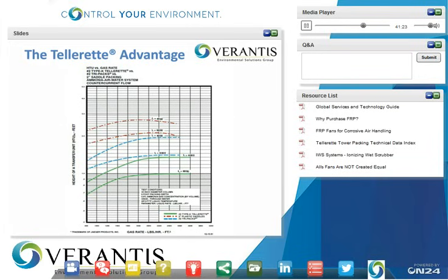To give you an example, again, I apologize, it's hard to read, but if you look at the gas rate at approximately 2,000 pounds per hour per square foot and a liquid rate of 4,000 pounds per hour per square foot, the Telluret system to achieve 99% efficiency would be about 6.4 feet of packing. Tri-pack would be 8.8 feet of packing, and the saddles would be almost double at 12.5 feet of packing. So the Tellurets are going to provide you the optimum performance for both pressure drop and for mass transfer. If you're replacing a fixed pack bed, what that means is you're going to get higher efficiency. You can get higher throughput if your process requires more flow, and it just gives you a lot of options for replacement.